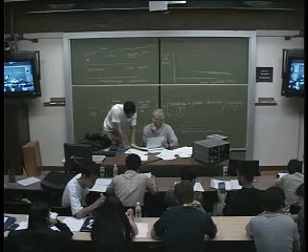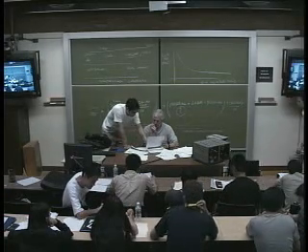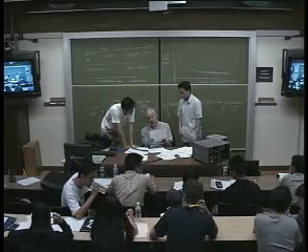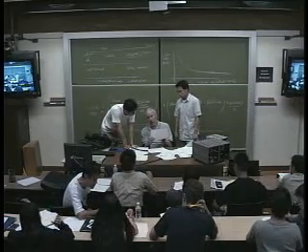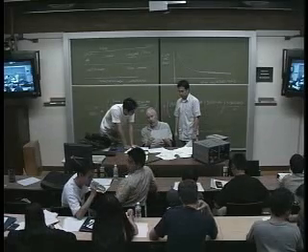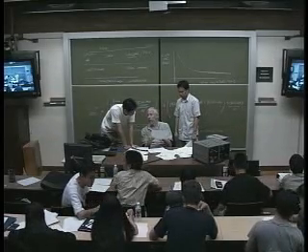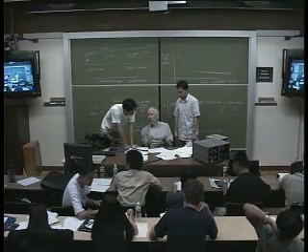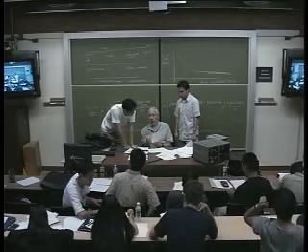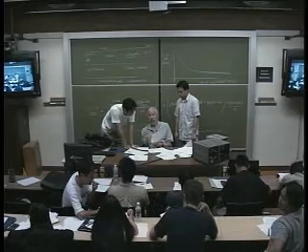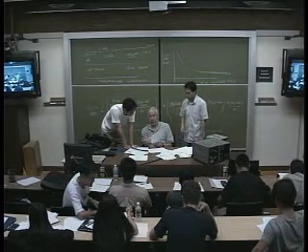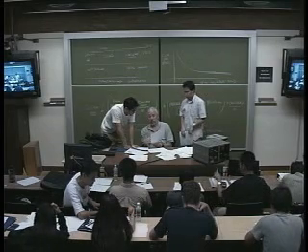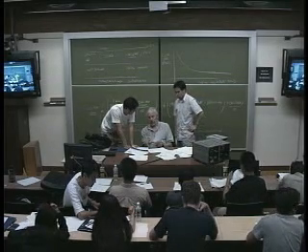Okay. Well, what else? You said you have a little bit of loss right here. What do you mean it's loss? Remember I said that all that current went upwards into the output eventually. Looking down it sees R0, looking up it sees 1 over GM. So there is a division between 1 over GM and R0 here, which loses a little bit of current, a little bit of gain. GM is reduced a little bit by that current division. It's not a perfect current source? Yes, because it's not a perfect current source, right? If this is a perfect current source, then we lose nothing through here. But it's really R0, right? So you lose a little bit of the current.